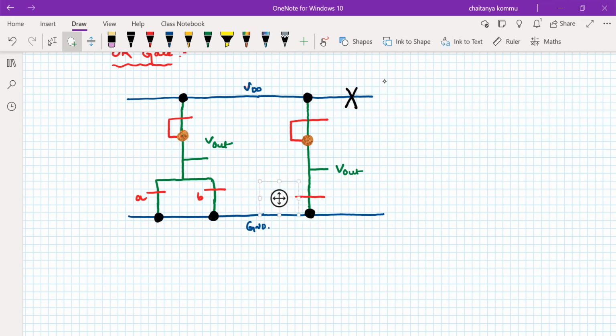So I have to connect this green line towards the red line, or I have to extend the polysilicon towards the green side. In this situation, metal is very suitable. In this situation, a metal contact is suitable. Therefore, I'm going to use a metal line here. It is a stick diagram, so I cannot draw something like this. Please remember, stick means something like this only. So I have to extend this one, extend this, and extend to this point.